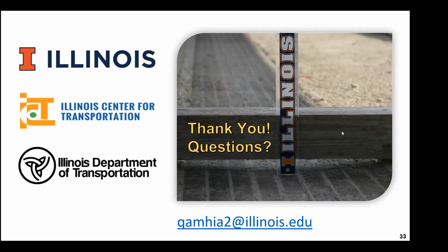So in such a setup that we did, what we have as a recommendation, if you want to do lab testing, something that is quick and less expensive, is that you probably do an accelerated curing of the material, so that instead of just 7 days at regular temperature, you cure them at higher temperatures or longer curing time, so that you are actually seeing more of what you will see in the field. So that's one thing that I forgot to mention.